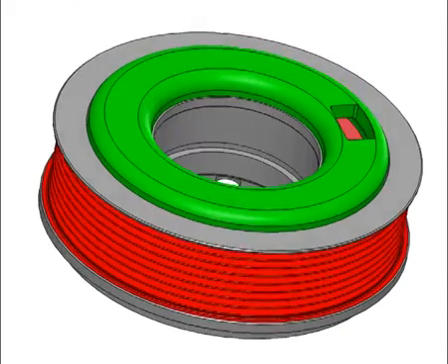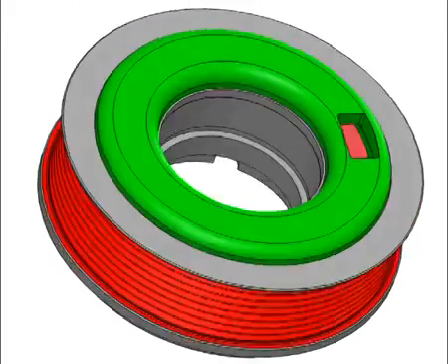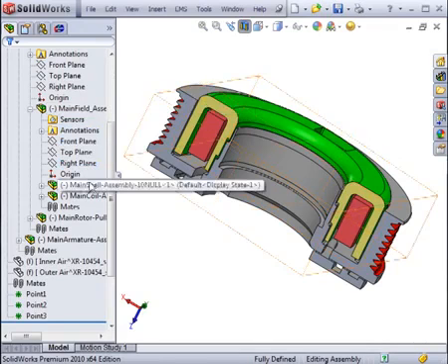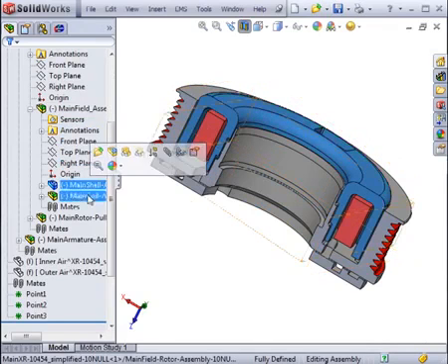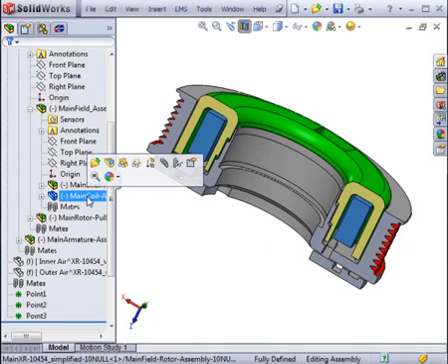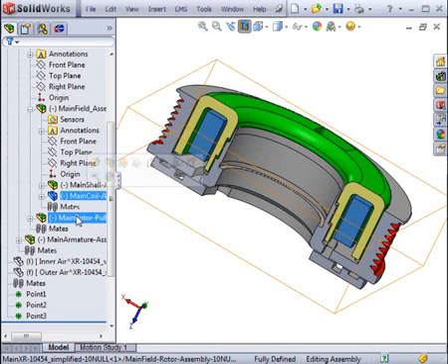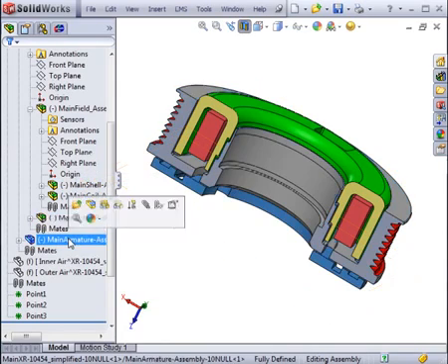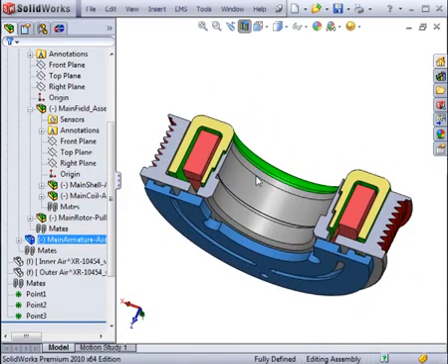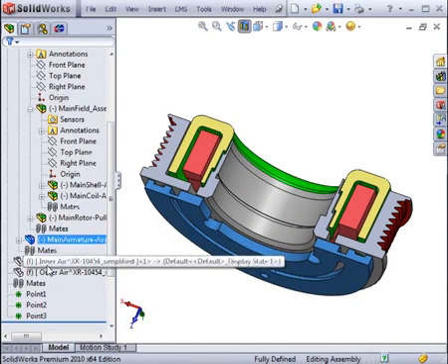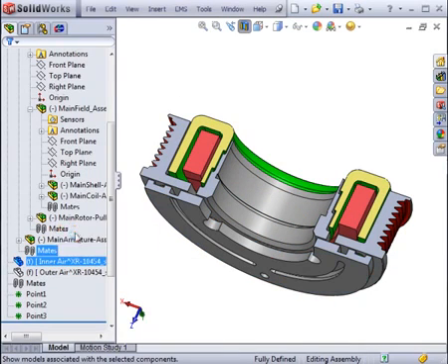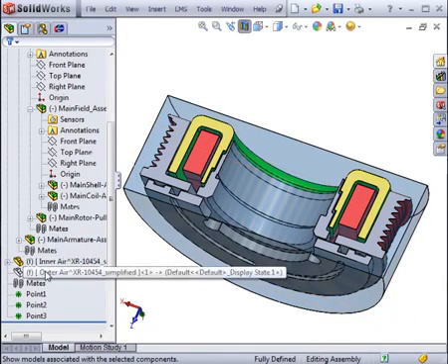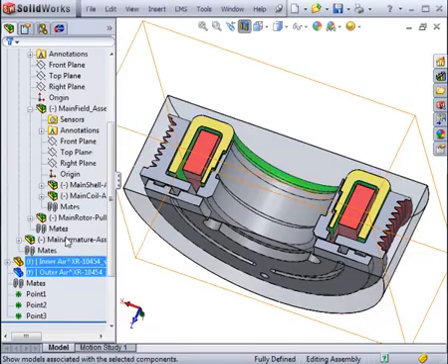This video tutorial focuses on designing and analyzing electromagnetic clutches. This clutch model is built in SOLIDWORKS and consists of a steel shell surrounding a copper coil. The entire subassembly is set inside a steel rotor, which has a steel armature placed under it. Two air components are also present. One shows the field close to the steel. The other acts as an infinite enclosure to take into account the smaller values of the field distributions.